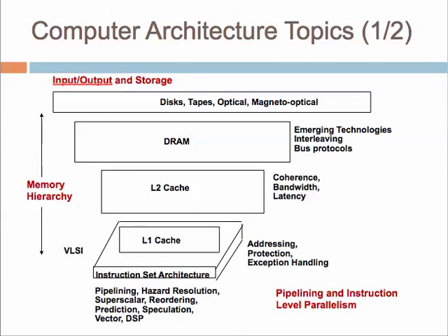And then when you go a layer down, you look at the instruction set. There are various ways of analyzing that. Then you go into the memory design, you look at the memory hierarchy. You have the L1 cache, which is the first level cache. You have L2 cache, which is the second level, larger. Today we can even have an L3 cache, right? Up to 6 to 8 megabytes of L3 cache is available.